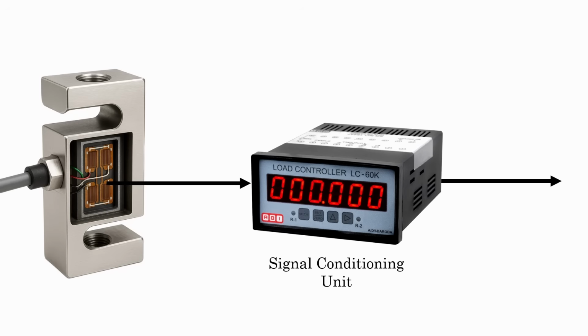So now when the load cell has no load, the sensor final output is 0 volt. And when it's loaded with 500 kg, the final output will be 10 volt. If it's a current output sensor, it will be 4 milliampere at no load and 20 milliampere at full load. Now the signal is strong enough to send to the PLC.